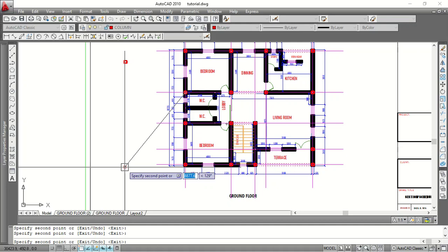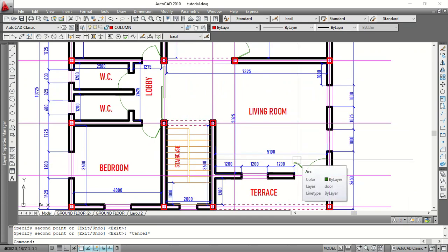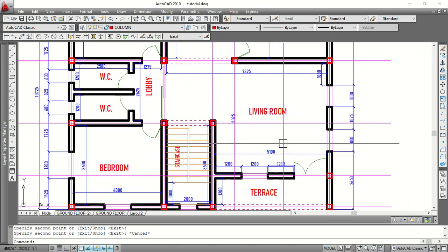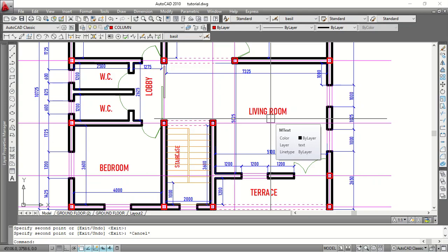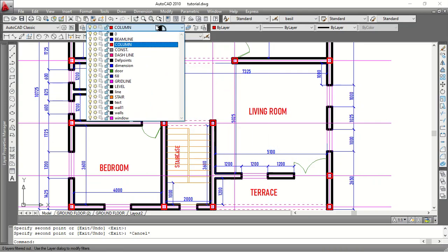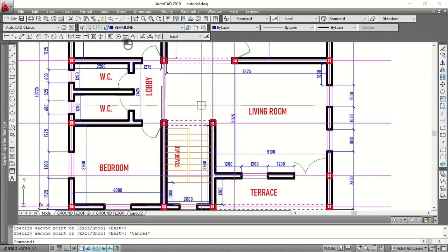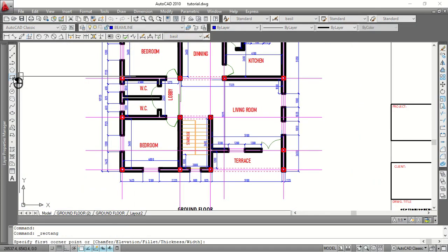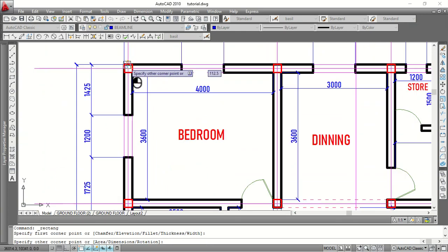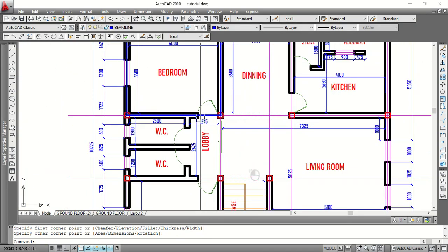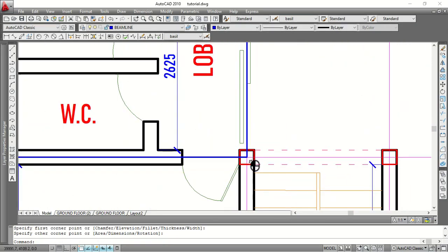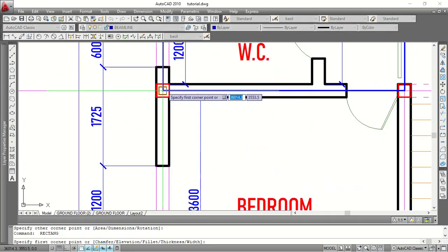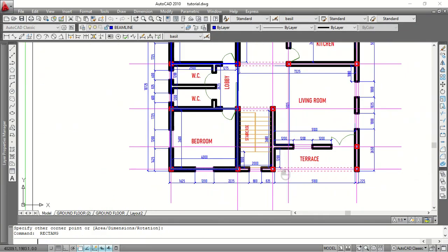Okay, so after this, what else am I going to be doing? Okay, fine. Based on my experience over time, let me not go here now. Let me just quickly bring out the beam so we can see the configuration of the general floor arrangement. So let me go quickly, pick a beam. Good. Now pick your rectangle tool. Just come at each midpoint to define the floor areas, one after the other. I'm defining each of them from their center point, one after the other.